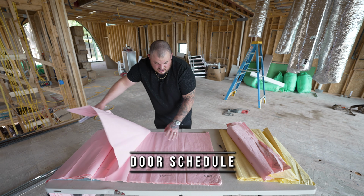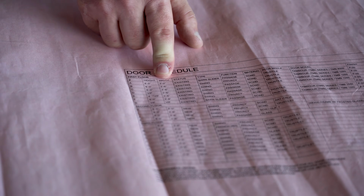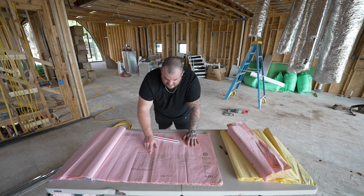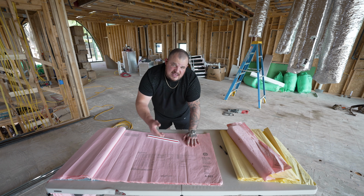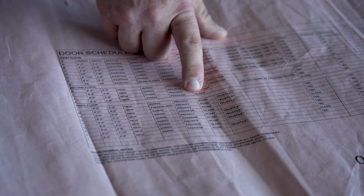So more windows here, but now here is our door schedule. Every single door is going to be called out by height and width. And also, it tells you the type. Is this a swing door? Is this a barn door? Is this a French door, which is double? Is this a pocket door? Also the function. Passage is a door that you can open without a lock. Privacy is one that would be on a bedroom or a bathroom that you can lock from the inside. Material. You either have solid core, hollow core. It's calling out glass. There's a lot of different materials.